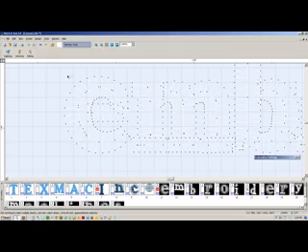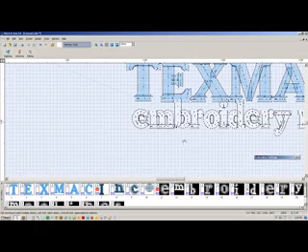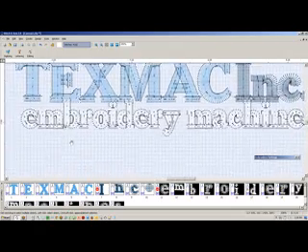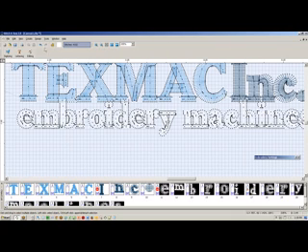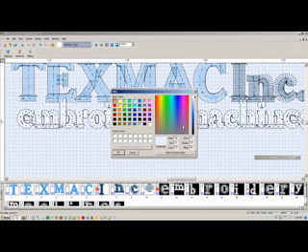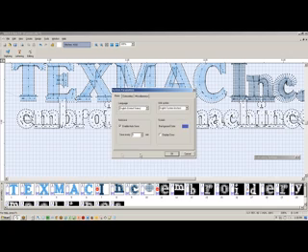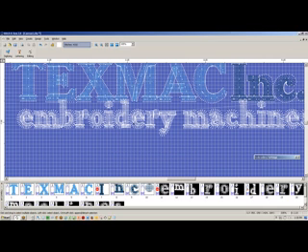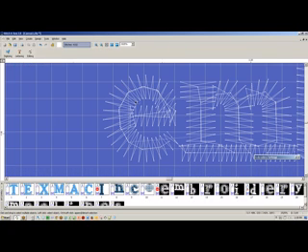Another problem, and let me go ahead, this is kind of obnoxious here, doing this white color. So let me set the background color to a darker, more contrasting color, so we can see a little bit better. Okay, all right, this is a little bit better. So you can see what we're looking at is the distance between the stitch points. Make sure that they're at least 1.5 blocks wide.